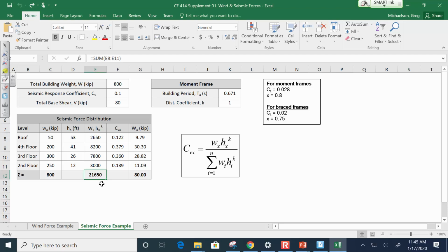Yeah. Well, your beams would be stretching a phenomenal amount, and what I'm saying is that steel beams just wouldn't stretch that amount. They would bend, but not stretch. If you remember from structural analysis, we did a frame example, and we did the frame deflection. Remember, if you consider the flexural deformations, it deflected like 5 inches, but if you consider the axial, it was like 5.01. Y'all remember that? I don't remember the exact numbers, but structures are very, very stiff axially, but flexurally, not so much.